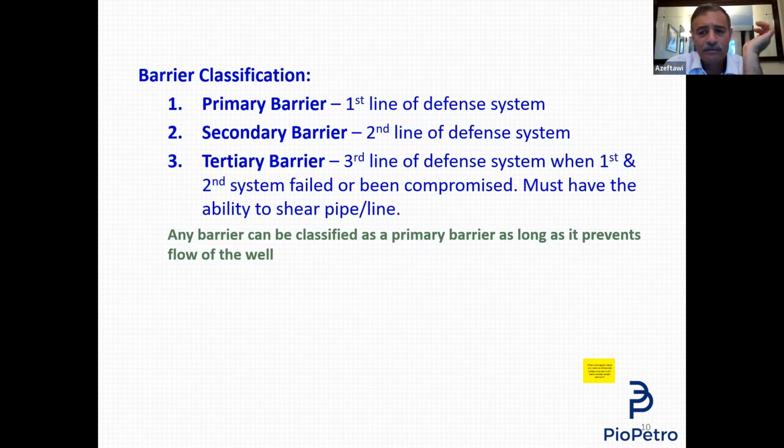Finished thinking already? Let me tell you. Some of you believe, yes, you can continue the job. Come on, Ahmed, it's just 20 psi. There is no harm. Some of you will say no. You tested your equipment before the job to 5,000 psi, so you are allowed to use this equipment up to 5,000 psi. If the pressure exceeds 5,000 psi by 1 psi, you cannot resume operation. You cannot continue, sorry.